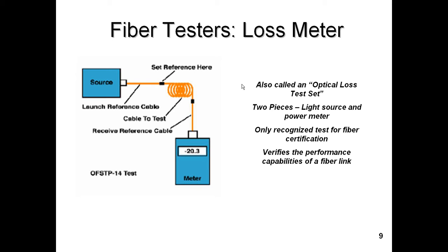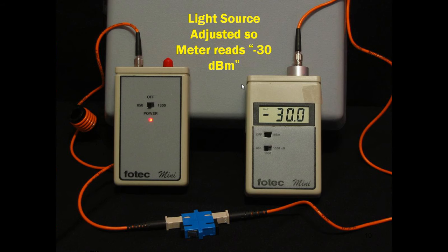And if, for example, we're testing 850 nanometers, as we are in this drawing, in this picture here, 850 nanometer multimode fiber is going to lose basically 3.5 dB of loss for every kilometer of fiber, or roughly 3,000 feet. You're going to lose half the signal in a multimode fiber.